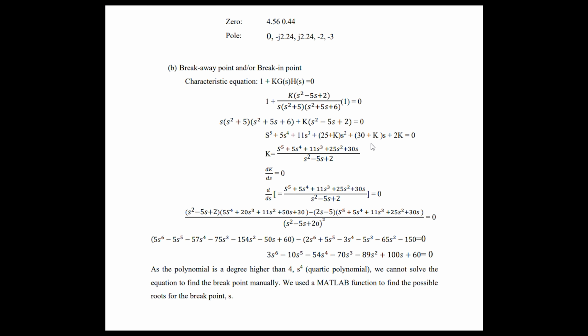Then we find the break point, or breaking point, by using the same formula, the characteristic equation, 1 plus G(s)H(s) equals 0.